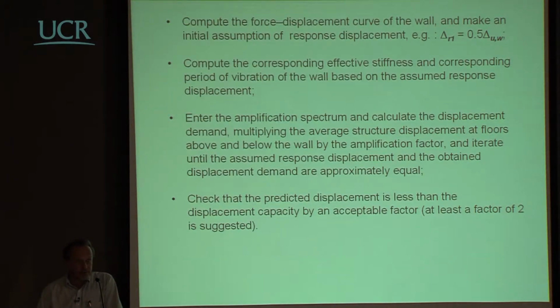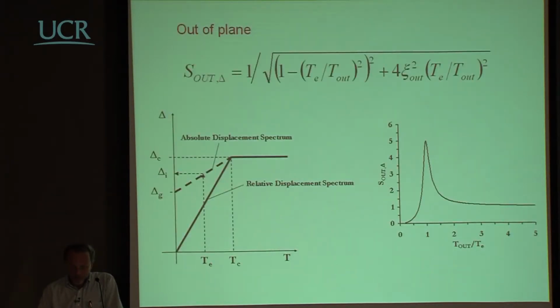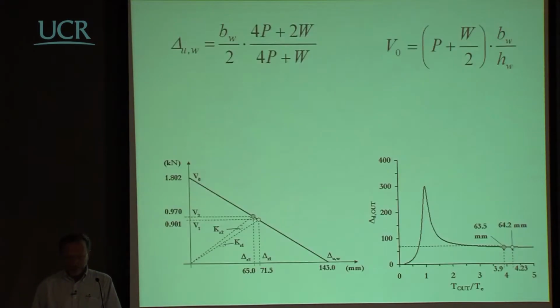Now, if you have this out-of-plane period of vibration, you can use it to enter here. That period of vibration is this period here. And you know the period of vibration of the in-plane response of your structure because you have already designed the structure in plane. So you will be able to plot something of this sort, which is the amplification factor of this plot, and therefore you will multiply this by this to have an actual displacement. And this is what is written here. And then you check whether the displacement that you have assumed is correct or not. So you do something like this.